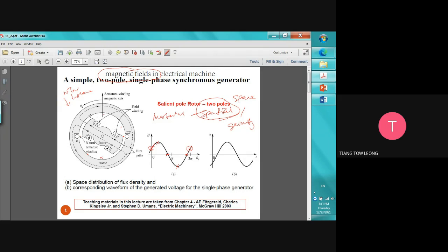So this is how we can find what the magnetic flux density is at this point, for example in this area, or this area. But the problem is we are not interested in that region. This is geometry, related to space. We are only interested in the middle of the air gap, because we want to know how good the magnetic flux is crossing from the rotor to the stator and then getting back to the rotor, so that it can cross with our winding.